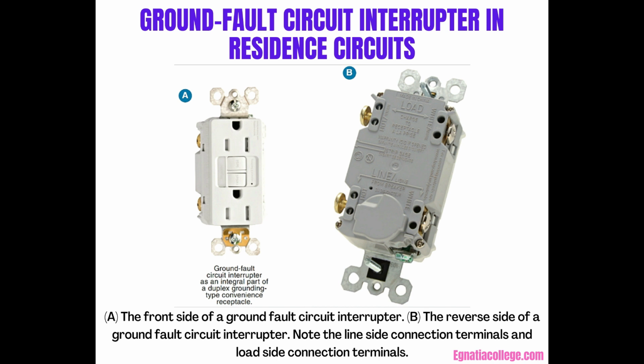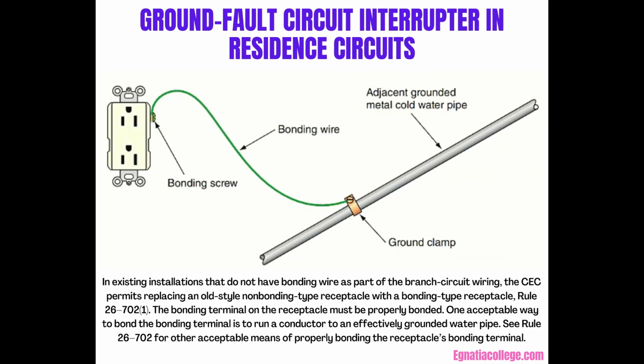When a GFCI feeds an isolation transformer, separate primary and secondary windings, as might be used for swimming pool underwater fixtures, the GFCI will not detect any ground faults on the secondary of the transformer. Long branch circuit runs can cause nuisance tripping of the GFCI due to leakage currents in the circuit wiring. GFCI receptacles at the point of use tend to minimize this problem. A circuit supplied by a GFCI circuit breaker in the main panel could cause nuisance tripping if the branch circuit is long. Some electricians say 15 meters or more can cause nuisance tripping of the GFCI breaker.